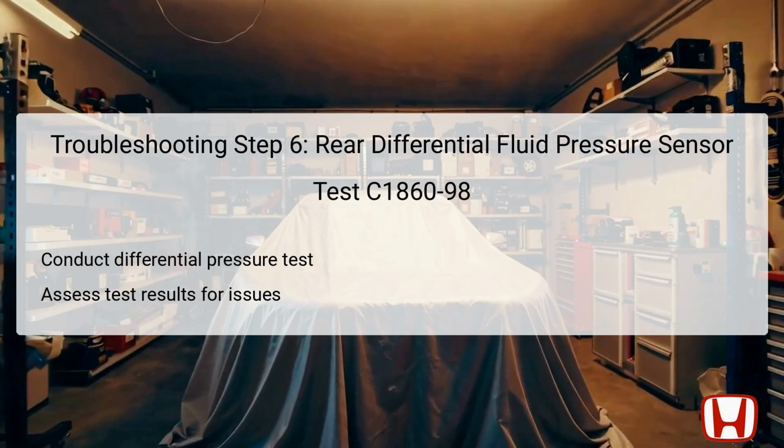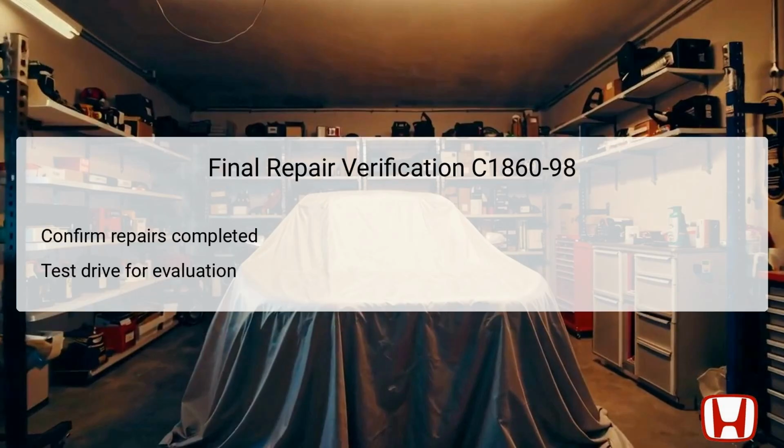Identifying the health of the fluid pressure sensor and ensuring it communicates accurately with the onboard diagnostic system is crucial to maintain the functionality of the AWD system and prevent overheating of the differential fluid. The final repair verification step is crucial after addressing the issues related to DTC C1860-98. This involves confirming that all necessary repairs and replacements, including any faulty sensors, brake adjustments, or tire issues, have